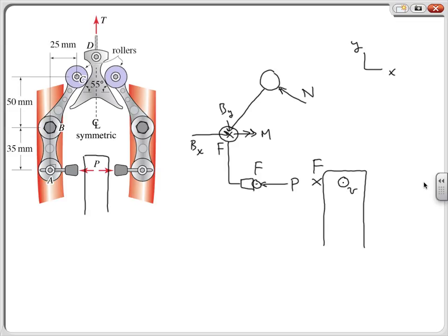And what will happen in this case is that we'll tend to get a peak location for the bending moment, which is now on the top segment right here. So now we should be able to actually see this. As opposed to the other locations, which were on the sides as a result of the planar loads, these out-of-plane loadings would tend to produce peak stresses and induce failures at the location that we've shown in blue here.